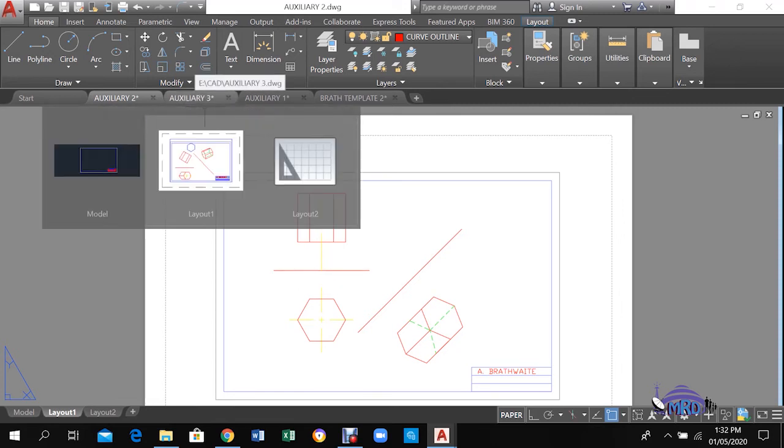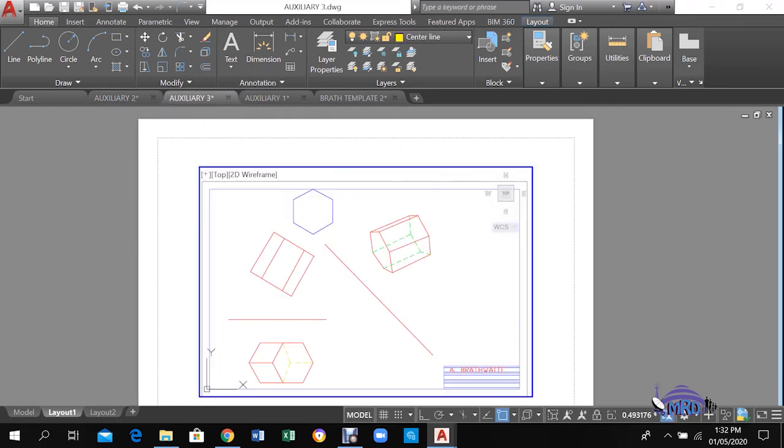Now we move on then to the final example, and this example, as the solution here will show you, is where we start to see what I was referring to as a flat three-dimensional drawing or flat pictorial drawing, because the auxiliary solution here kind of looks like an isometric type drawing. So remember, it is still orthographic projection. It is just that because of the orientation and the angle at which we're viewing from, we end up with a shape that looks like this.